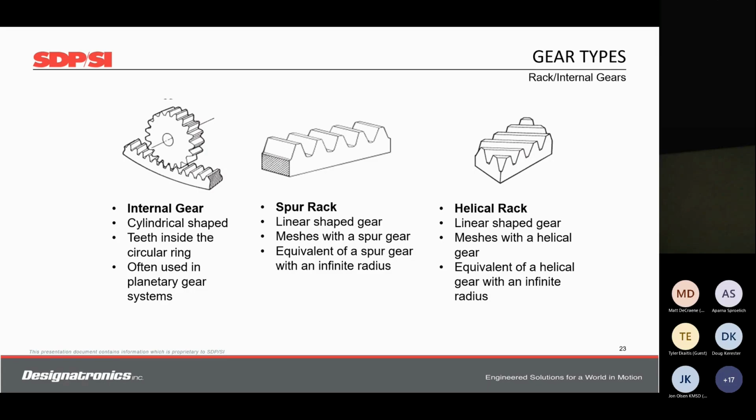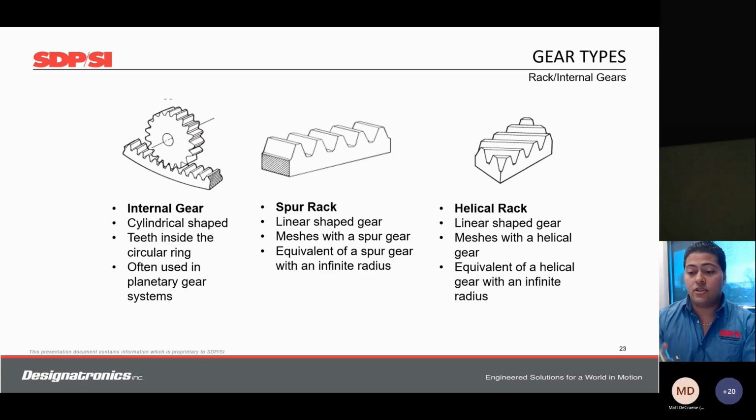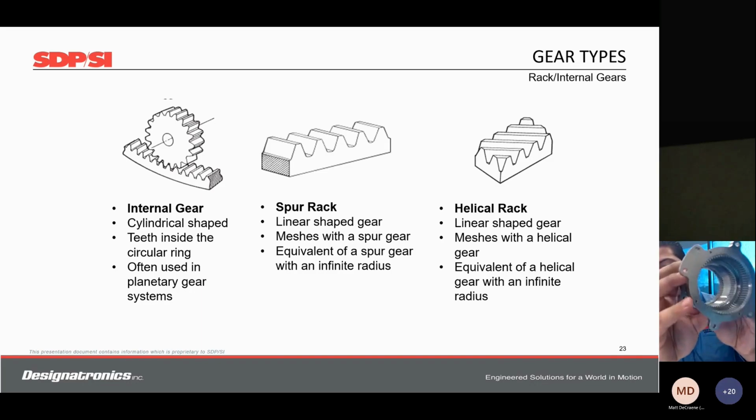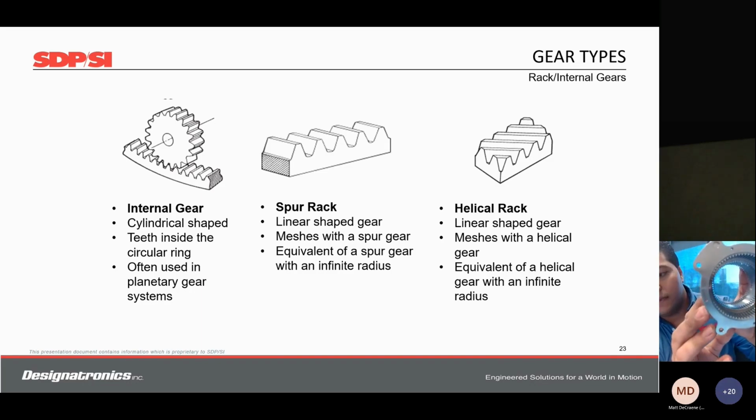Here's an example of an internal gear, but one that's already incorporated into the housing. This particular housing has 3 internal gears already incorporated into the design. And this was done by shaping, a manufacturing method which we will talk about later. This side was done first, followed by this internal side with a different shaper, flipped over and shaped for the 3rd internal gear.